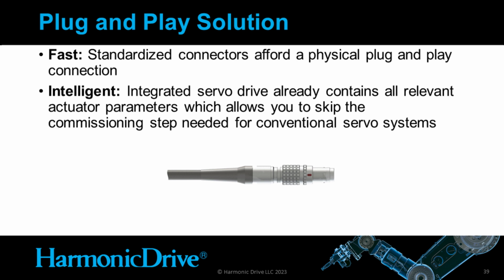So a little more detail on this. The plug-and-play solution, servo drives with integrated actuators are fast and intelligent. Their standardized connectors afford a physical plug-and-play connection. So if you have to change your size from one to another, odds are you can just unplug the cable and plug it back in to the new one. And the intelligence of them is that they already contain all their relevant actuator parameters, which allows you to skip the commissioning step that's needed for conventional servo systems.